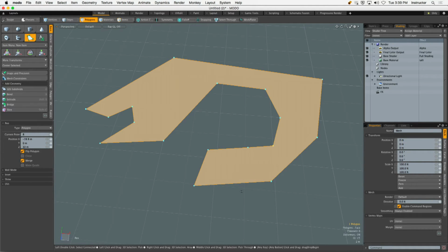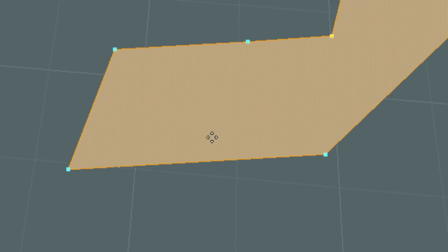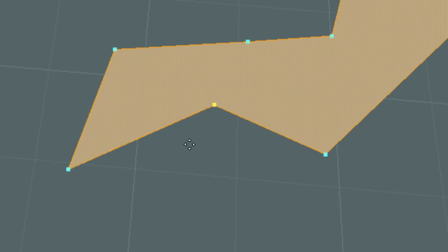So if I wanted to create a new control point in here, which of these two would I need to select? It's always going to be created after. So if I wanted to create a new control point kind of where that cube is, I'd select the rightmost control vert. Think of it like we're going around, drawing our shapes in a clockwise manner. So if I grab that one, and now when I click in here, it creates the shape that I'm after.